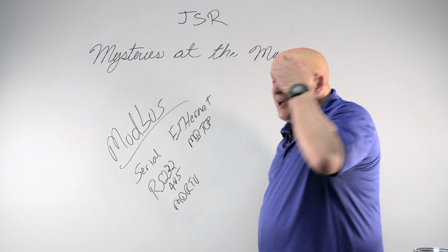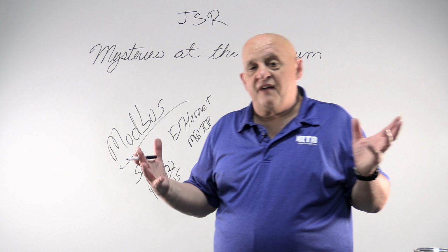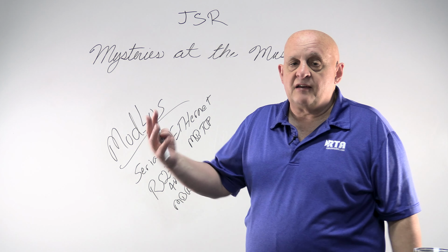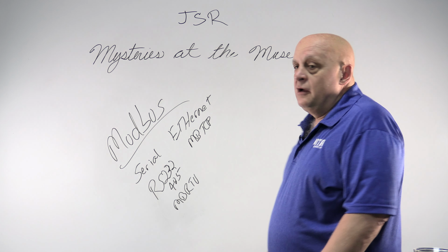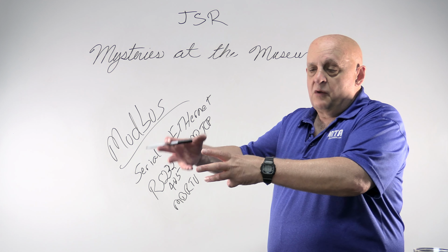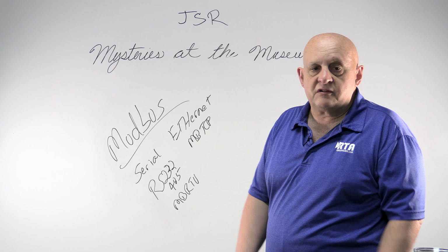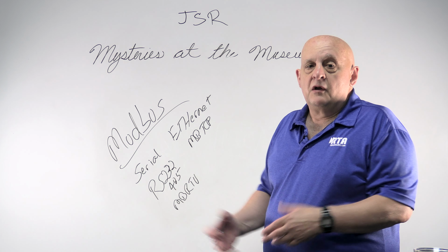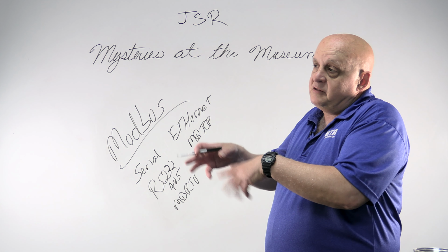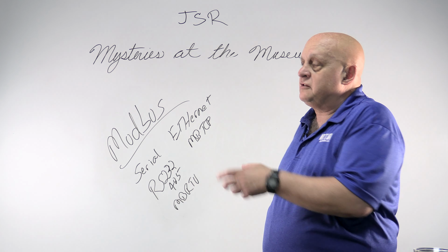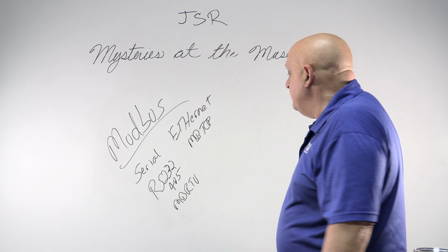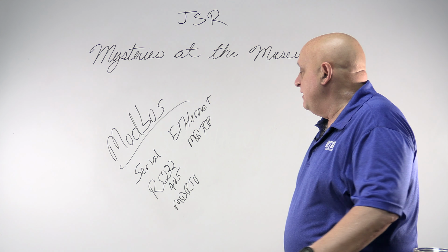The big thing about Modbus is every device looks like 4 groups of 64K unsigned integer registers. So you say, I want to read this register set, this offset, and I want to read or write 16 bits of unsigned data. It only had one data type. What applications would do is take that data type and say, well, it's unsigned, but I'm going to use it as decimal, or I'm going to use 4 of these as floating point, or whatever you want to do. So they would define it differently.